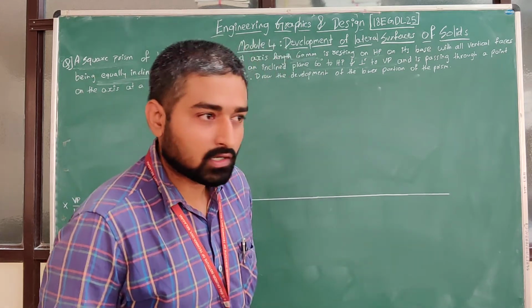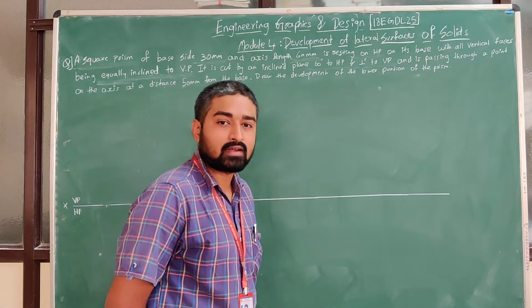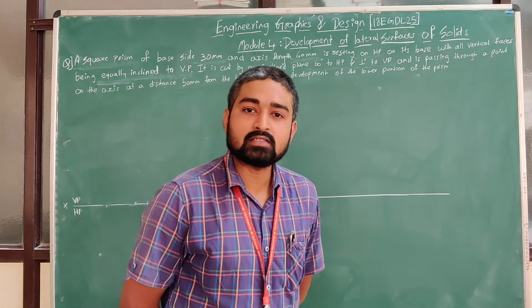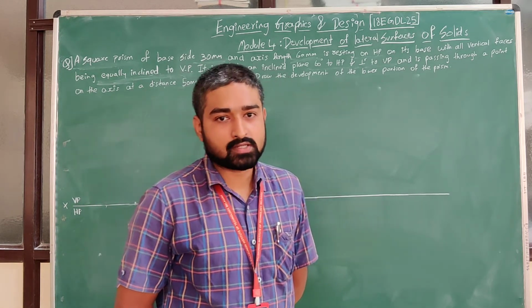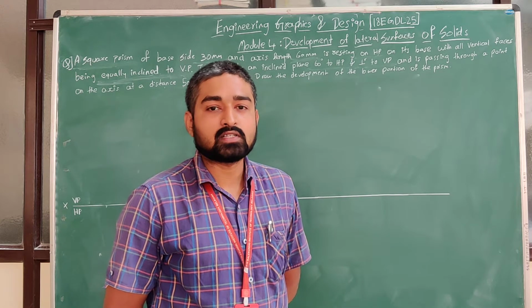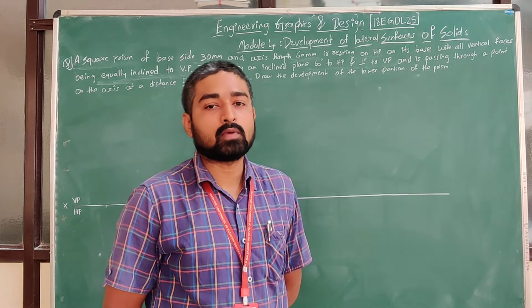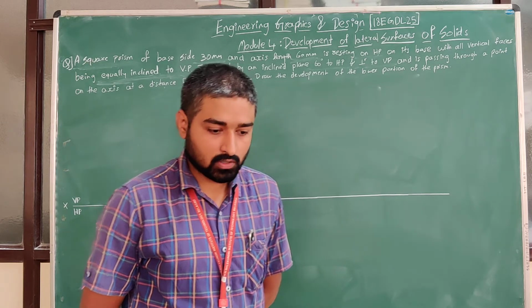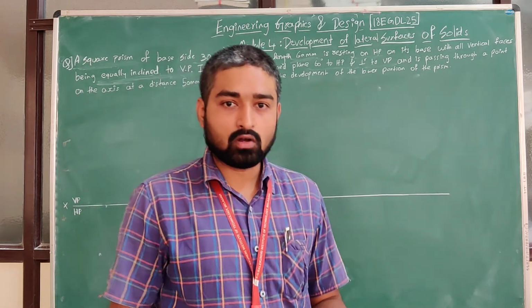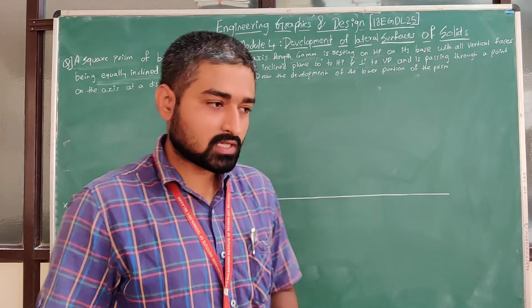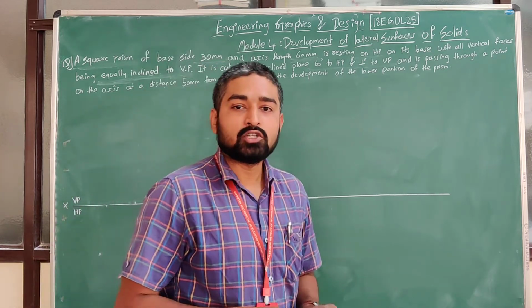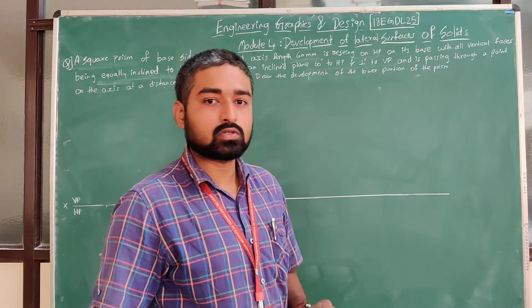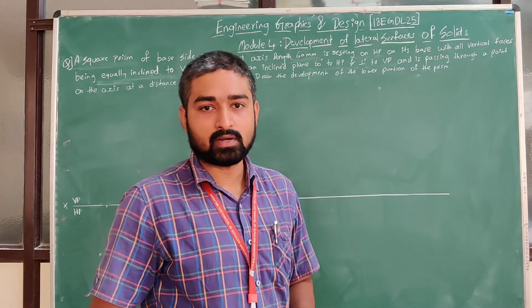Okay, so in today's topic, development of lateral surface of solids, what do you mean by development? Development is nothing but when you cut open those solids, either a square prism or a rectangle prism, or a pyramid, how does it actually look? It looks just like a sheet, so how are you going to develop that? This has very important applications in sheet metal industries. If anybody is developing a sheet, those applications are many in developments, right?